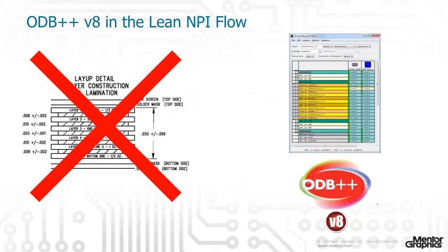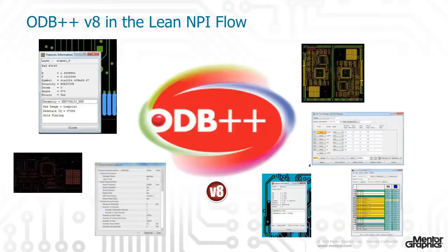The stack-up drawing data is included in the ODB++, shown here with examples of the dielectric requirements, including bulk resistivity and loss tangent for the dielectric layers and the copper weights for the conductive layers. When a complete product NPI process has been carried out, there is much more to the ODB++ than being an alternative to Gerber. Instead, it delivers a complete definition of what has to be manufactured, including all the information traditionally carried in paper or PDF documents, but now integrated into the structured data ready for immediate and automatic use by the next software tools in the flow.